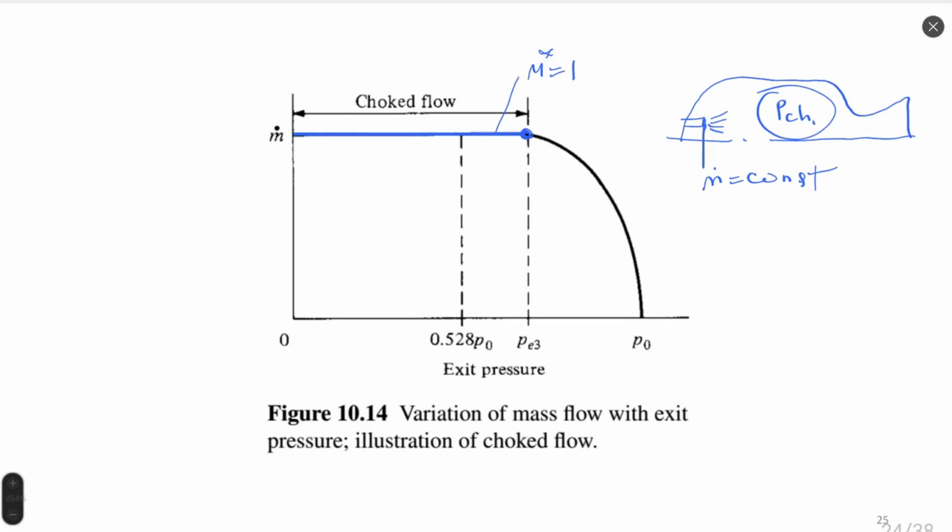You can change it by changing the relation between oxidizer and fuel, or the contraction ratio of the nozzle if it's a regulated or controlled nozzle. You can change the pressure inside the combustion chamber in different ways, but the mass flow rate can be independent of this pressure if you create conditions where the feeding pressure is 2 times higher than the chamber pressure.